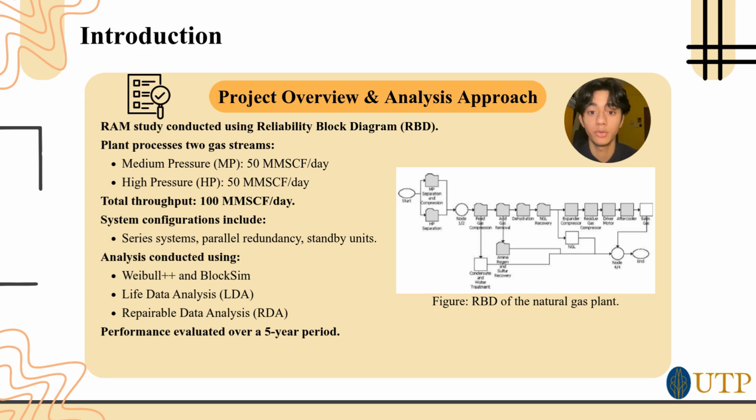Next, for project overview and analysis approach, in this project, a reliability, availability, and maintainability, or RAM as you can call it, study is conducted based on a reliability block diagram model. The plant processes two gas streams, a medium pressure stream and a high pressure stream, each contributing 50 mmSCF per day, resulting in a total output of 100 mmSCF per day.